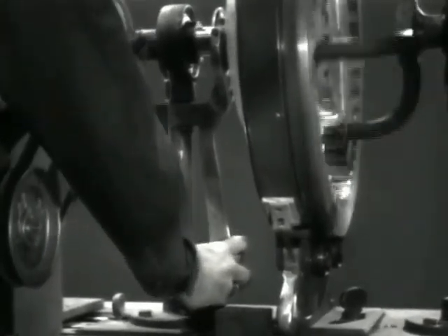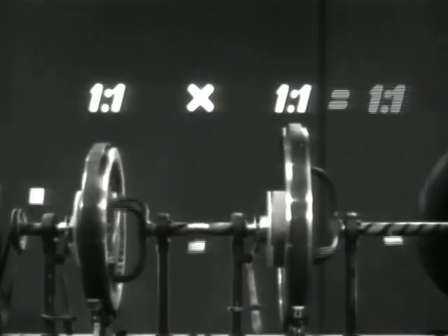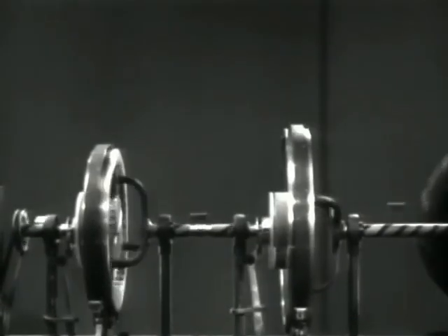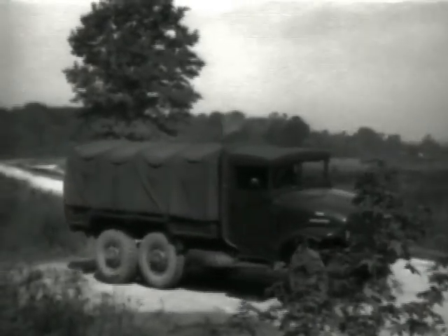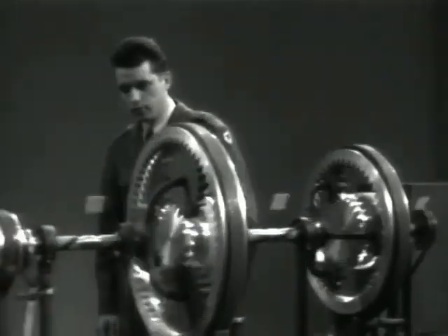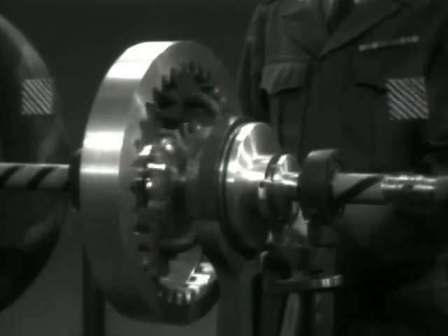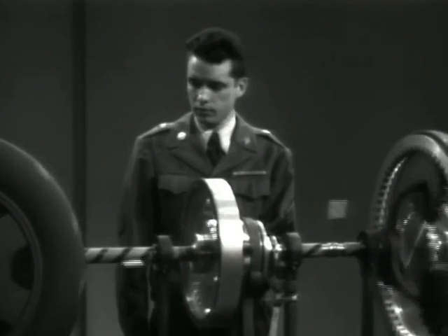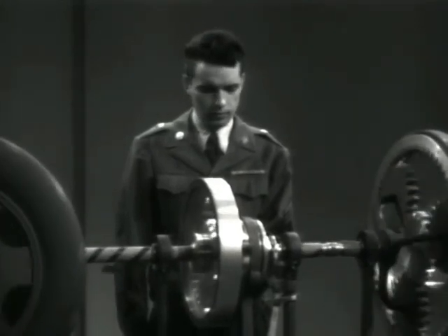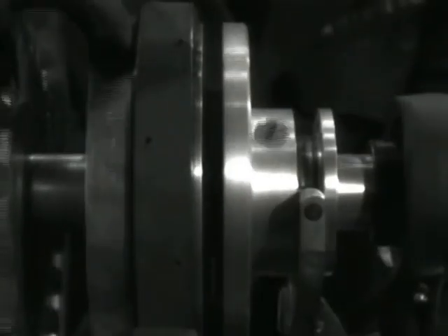With both sets of gears placed in direct drive, we get a ratio of 1 to 1, with no gear reduction. That's fine for forward, but vehicles have to back up too. How do we get reverse? Well, to our 2 sets, we could hook up a simple reverse set. With the planet carrier made reactionary by a band, this would give us reverse. We could also transmit forward through the simple reverse set by putting it in direct drive.